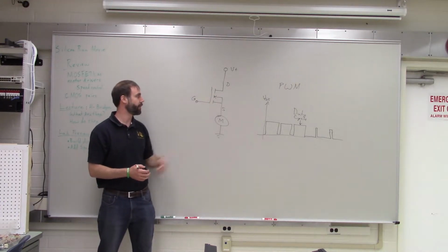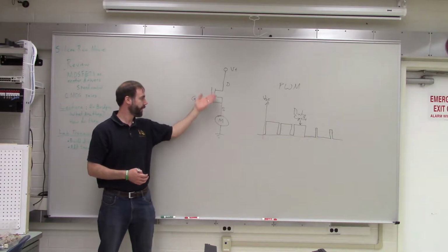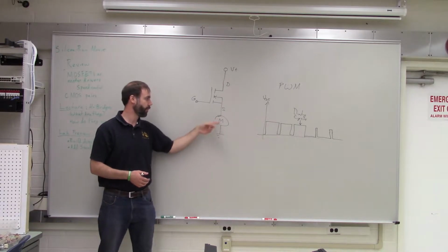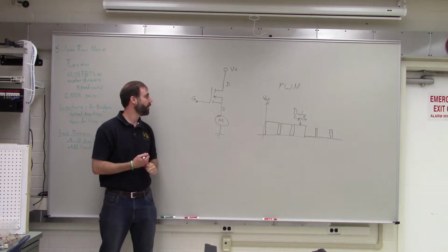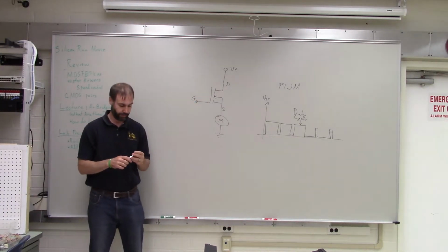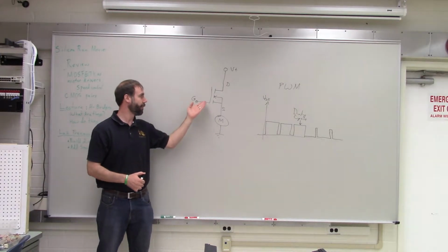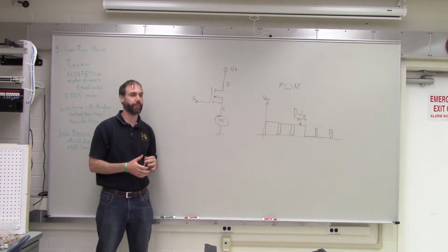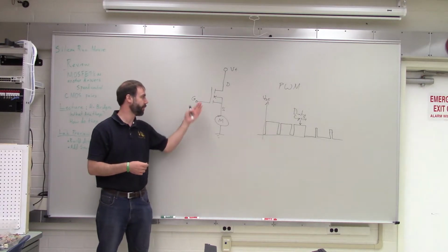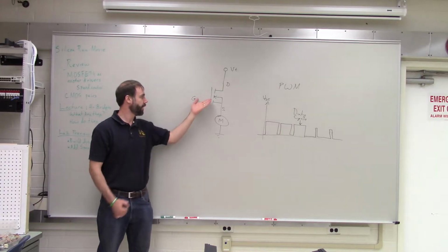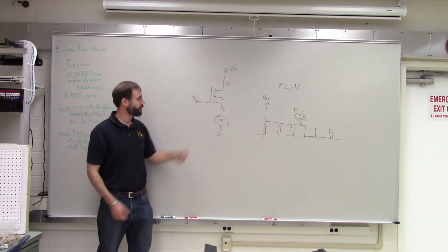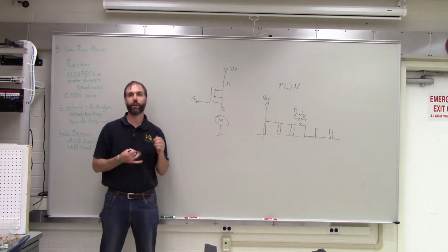It turns that power into heat. And so that's wasteful because it's energy that's not doing what you want. It's not moving the motor, and it's also hard to deal with that heat, right? You have to dissipate it in some way. If you have lots of these things together, then your device might heat up, and it might become dangerous to people. It might start melting solder. So it's just inefficient. So the MOSFETs are really most efficient when they're either fully on or fully off.